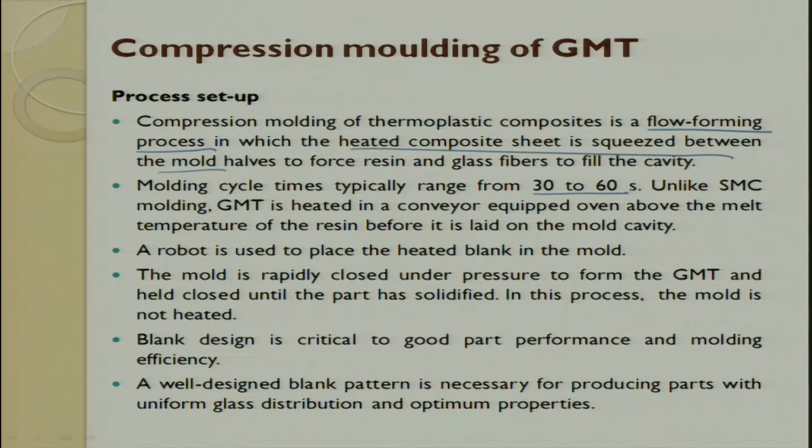Then afterwards the mold is maintained at heat for 30 to 60 seconds. Then the mold is rapidly closed under very high pressure. After this very high pressure, the part gets properly consolidated and then we try to get the required output. So first, the compression molding of the thermoplastic composite is a flow forming process, correct, because